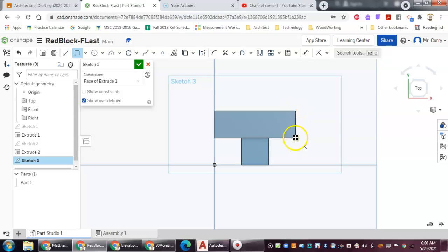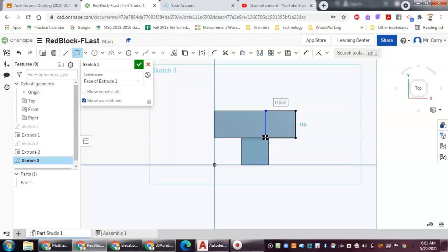Pick up on either one of these corners will work. So, and of course, I'm going to come right over here. I'm just going to make sure, notice how it highlights the line. So now I snap in, and I'm setting a constraint with this rectangle to be tied in both up here at this corner and that line. I could also just drop it here and then change my dimension. Either way, but you're automatically giving it that 0.5 when you're picking off of another geometric component on the part. So let's go ahead, and I'll just click there. And then, of course, I need to change this to 0.5 and hit enter. I'm already at 0.5, so we're good to go, but it gives you the option. You can still enter it if you want.